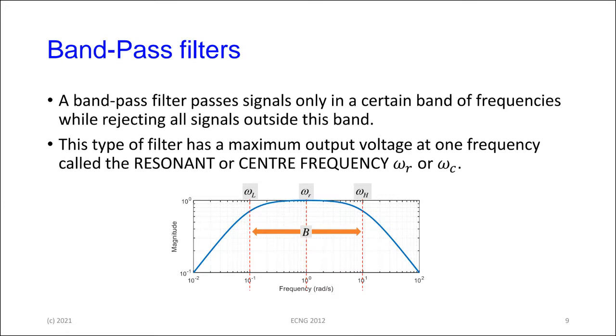So a typical audio amplifier, or a small signal amplifier that you would have learned to design, for instance, in level 1, has a frequency range. It will run from some low to some high frequency, and outside of that is not going to work. Similarly, an audio amplifier that you have for your own use is supposed to pass frequencies between 20 hertz and 20 kilohertz, but it has a very poor response outside of those. So inherently, those behave as bandpass filters.